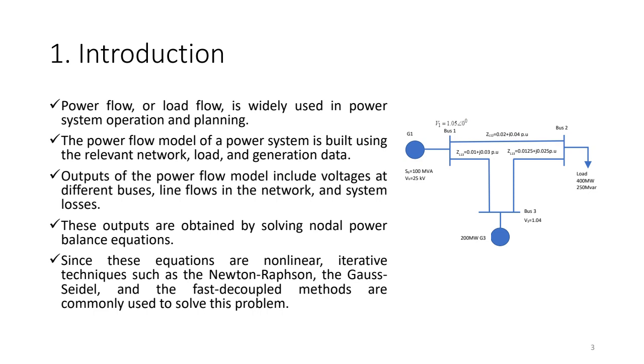There are a lot of methods available to solve the load flow. One of them is Newton-Raphson, and the others are Gauss-Seidel and the fast decoupled method. But mostly the preferable method used by all the software is the Newton-Raphson method. So for this course, we stick to the Newton-Raphson method of load flow analysis.